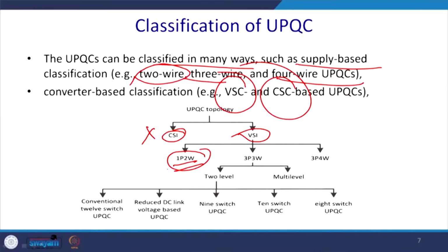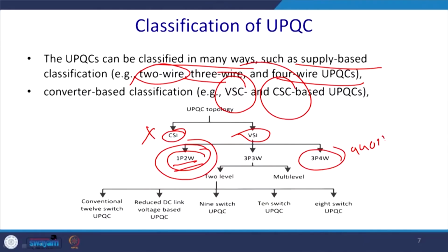So, for this reason commercialization has a great challenge to use this UPQC for this level, and for this reason we generally prefer the 3-phase 4-wire system with a neutral connected, and we mitigate a load for the 3-phase 4-wire system, and there we may have different kinds of voltage levels. Generally the 3-phase 4-wire system has a 440 volt line. So, there we can have a load up to around 10 kilowatt or more than that.